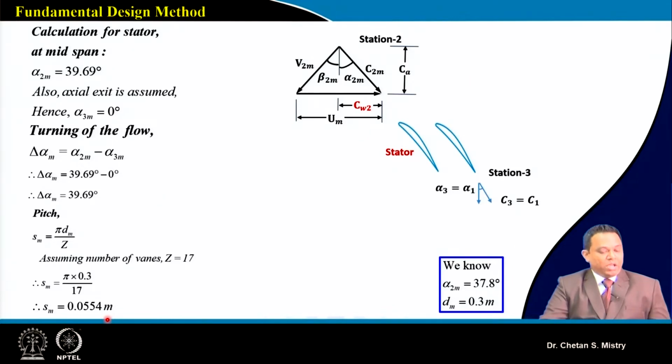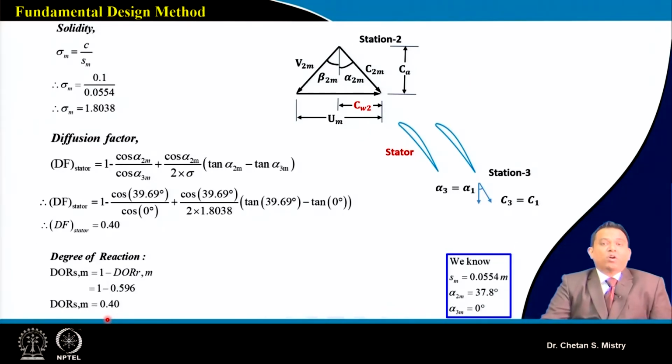Now, based on our available chord of 0.1 meter, we can calculate the solidity at the mid station, and we can calculate the diffusion factor for the stator.